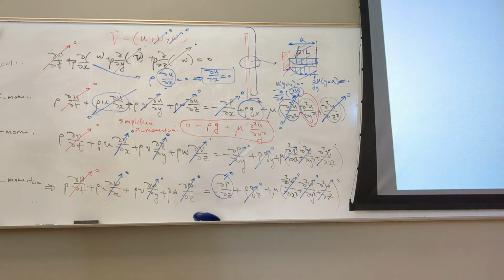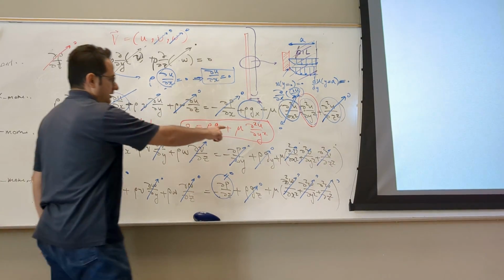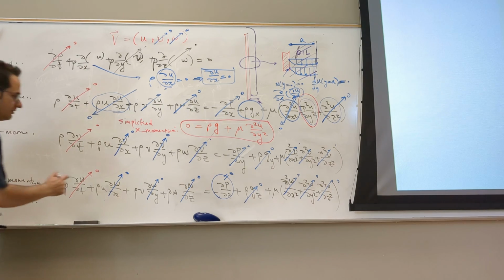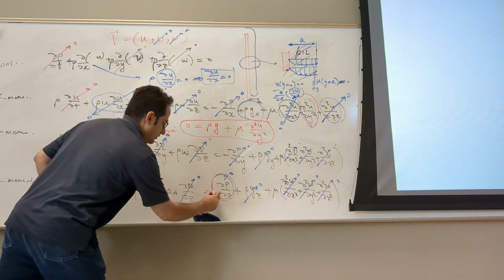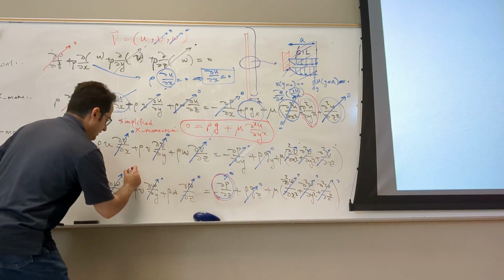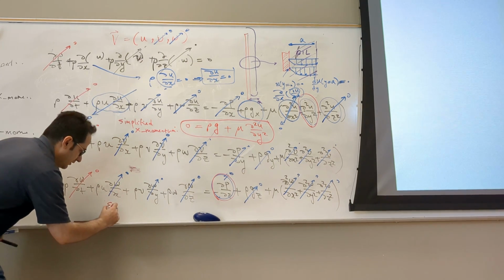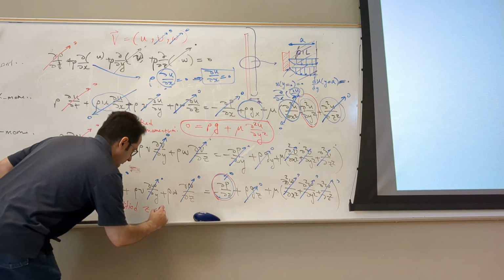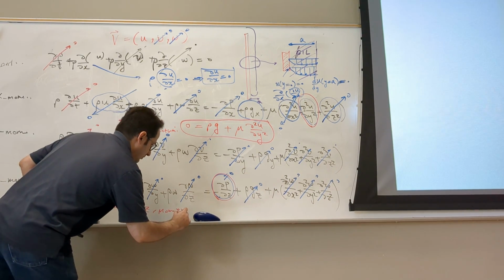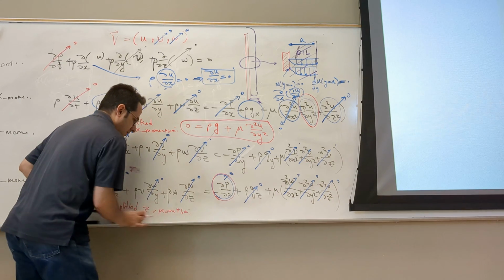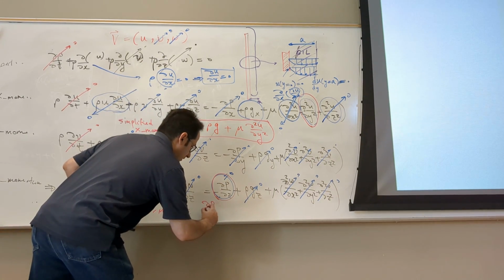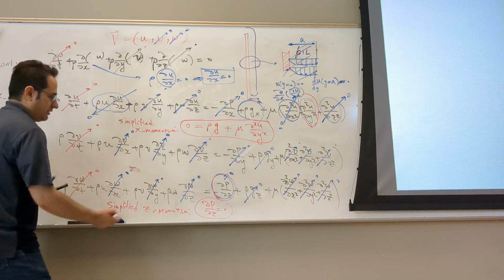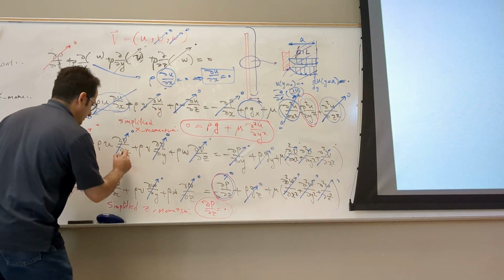Mu times the second derivative of u with respect to y. Now, simplified y momentum is what? This guy must be 0. This is simplified z momentum. Let's put it here, simplified z momentum. It gives you the pressure gradient in z is 0, which makes sense according to the physical interpretation.